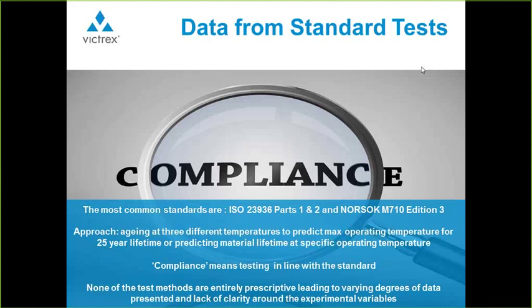And it's important to mention there that that's a material lifetime and not actually a component lifetime. As Alexandra has said, it's very important to remember that these are not pass-fail standards. They're simply test methods like any other, for example, like testing to ISO 527 for your tensile properties. And they describe ways of presenting the data.